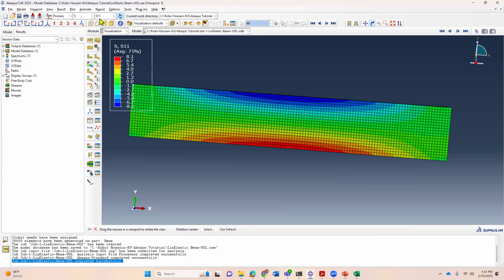What the first one after S indicates is the axis to which my plane is perpendicular. So X is 1, Y is 2, and Z is 3. That means my plane is perpendicular to X, which is 1, the X-axis. That means vertical section. And the second number here indicates the stress direction. So the section is vertical, that means beam cross section, and the stress is in X direction. So that's definitely longitudinal stress.